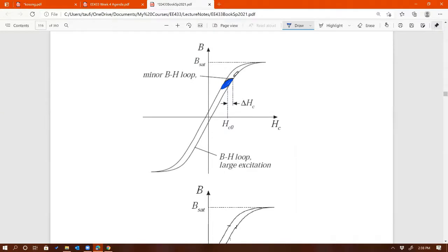Positive change in the component and a negative change in the component, just like the inductor current that we have earlier, right? From here to here, that's a positive change. And from the peak back to the minimum, that's a negative change. But you can see the current and the voltage stay positive. It always stays above 0. That's why it's taking up only one quadrant for this kind of operation, right?